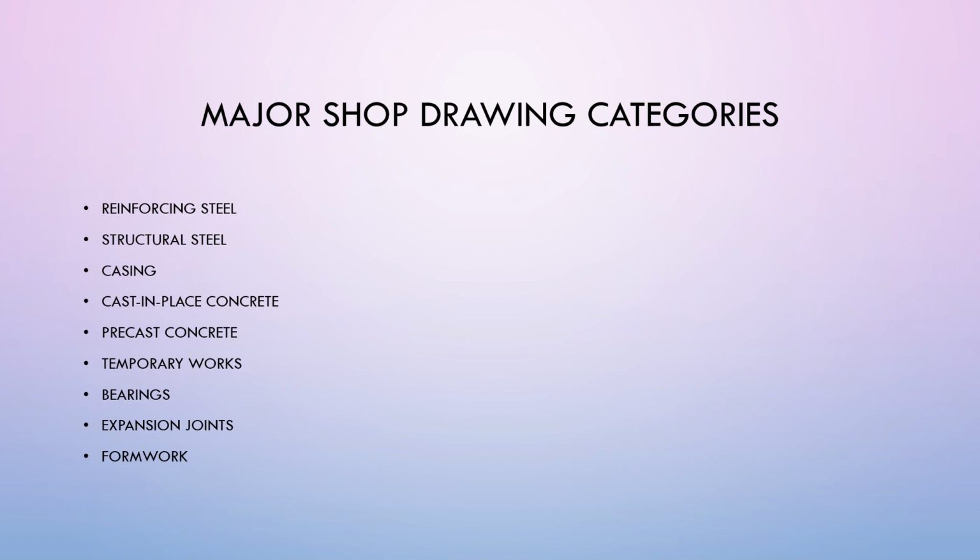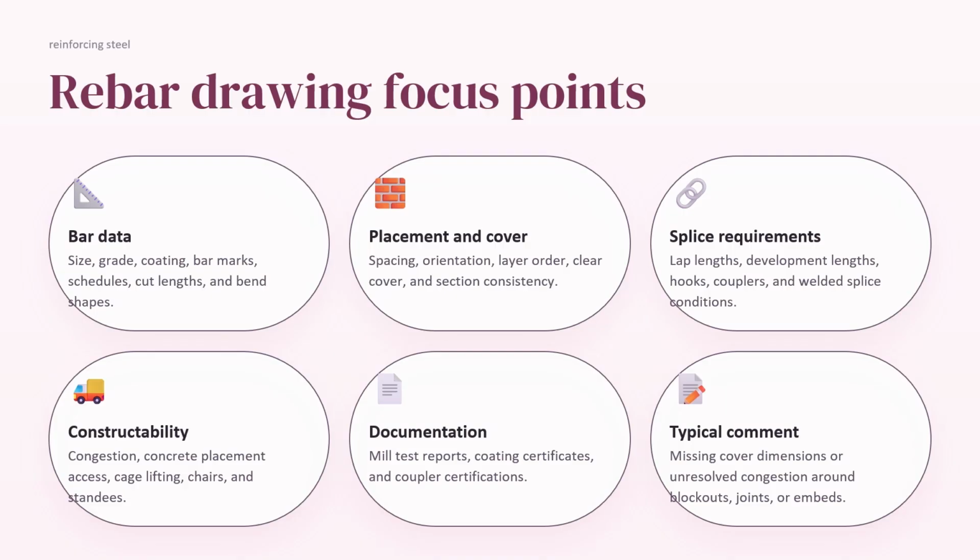Reinforcing steel, structural steel, casing, cast-in-place concrete, precast concrete, temporary works, bearings, expansion joints, foam work. Rebar drawing focus points. For bar data, you need to check the size, grade, coating, bar marks, schedules, cut lengths,